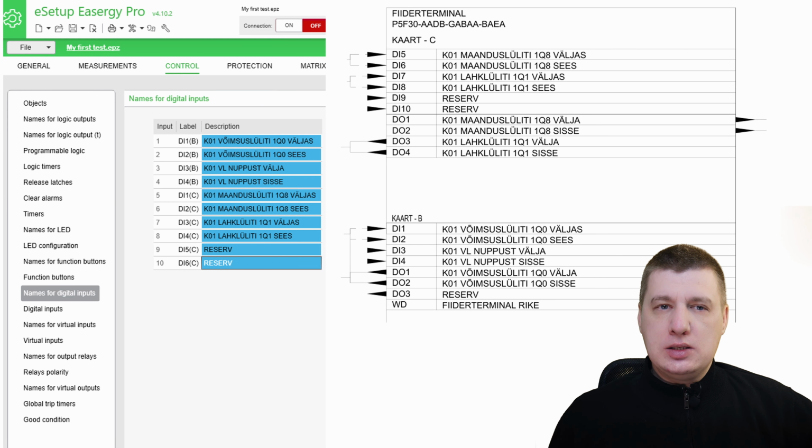In the system, every digital input has two distinct naming fields. First, there is the label. This is a short identifier limited to a maximum of 10 characters, specifically designed to fit on the relay's local LCD screen. Second, there is the description. This can be up to 31 characters and provides a more detailed explanation for the user working with the brand software.